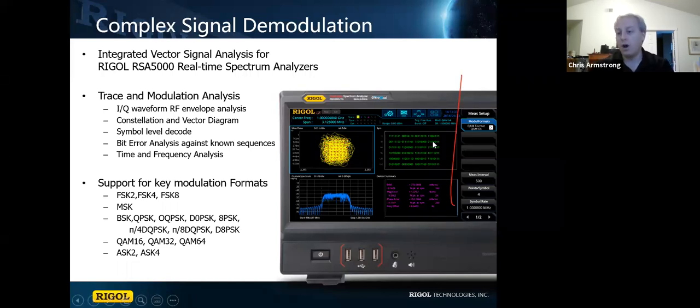And so if you know the signal you're transmitting, you can go all the way through this process and say, okay, I'm expecting this 100-bit sequence, and this is the one I'm getting. So you can do error rate analysis. You can set it up to trigger on a bit sequence to start, look at the whole sequence and compare the error rate.